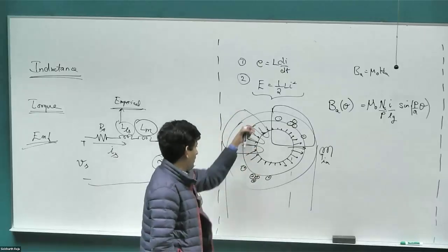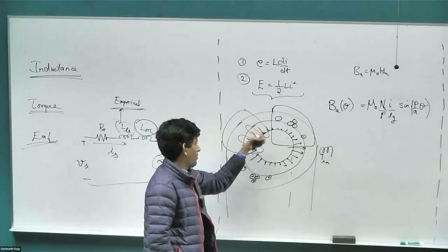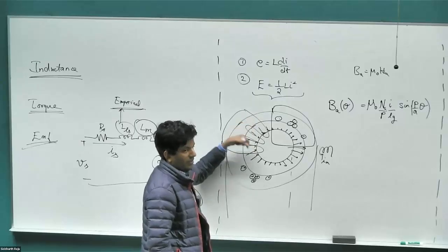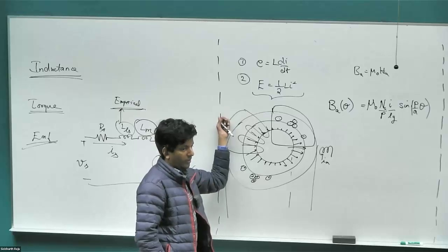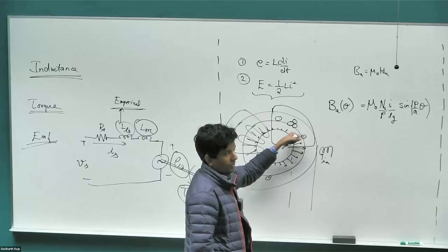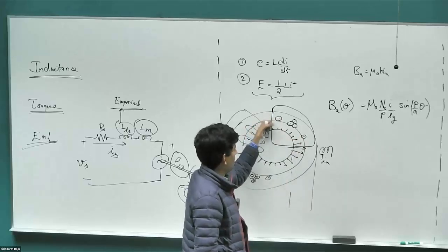Right? So every time you cross the air gap, it will be an integral H dot dl. Each of that would contribute to an Lg. But the problem is if I choose a loop like this, I don't know what this H is here, and here. I have a single equation, but 1, 2, 3, 4, 5, 6 H that I need to calculate, which I can't. But if I choose the symmetric loop, I know the H here. So I can, because at least I know that they have to be the same. So I can pull that out common, and then there's one Lg.